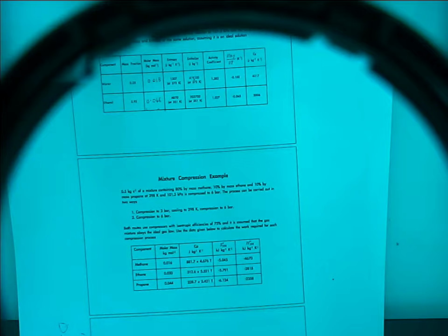And why is that? Because imagine that you are given a certain mixture at this temperature and pressure. They're not going to give you, oh, here is the ambient temperature and pressure of the mixture. So you will have to search for that data. You will have to find something as a reference to start your calculations. So you will look in enthalpy charts, you will look in different types of sources when they give you the data of enthalpy and entropy.